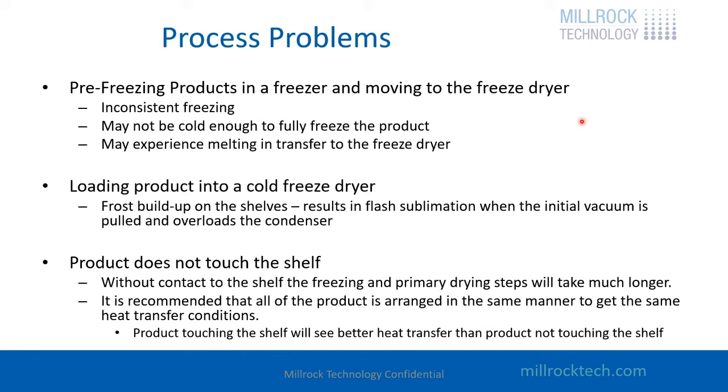There's also the case where product does not touch the shelf. If you're freeze drying in bags or you're freeze drying in medical devices, you might have some product touching the shelf, some product not touching the shelf, or none of the product touches the shelf. What we recommend in those cases is if some of the product never touches the shelf, then none of the product should touch the shelf, so you have consistent heat transfer across your batch. All right, so it's very important to understand that everything should freeze at the same rate and everything should dry at the same rate.